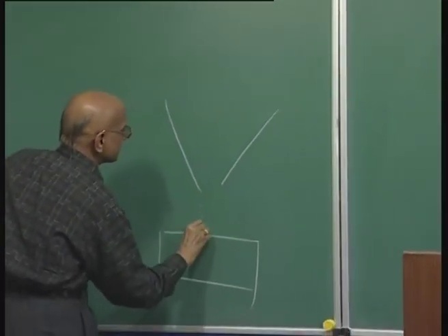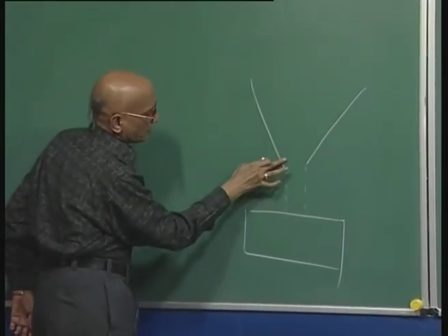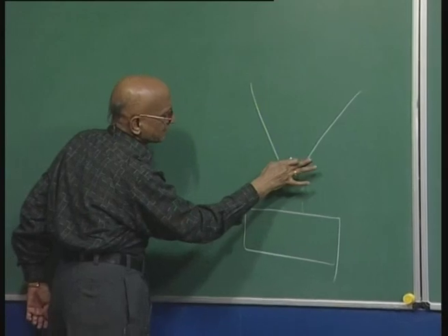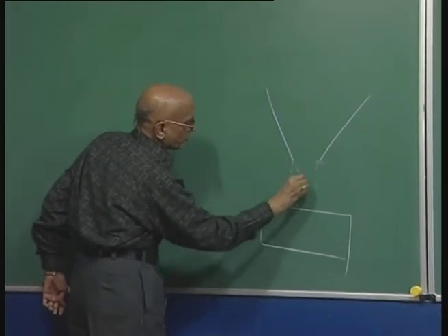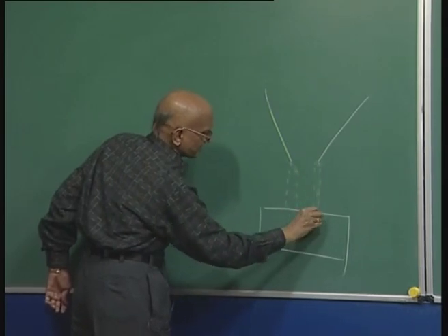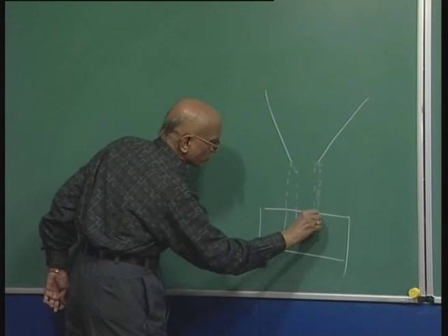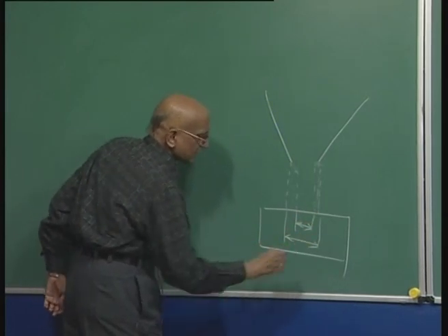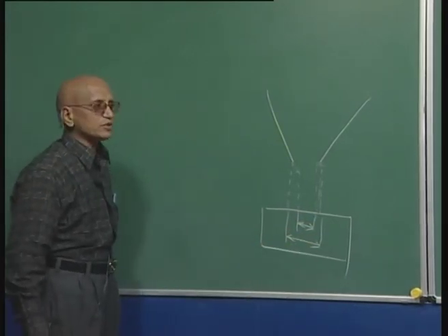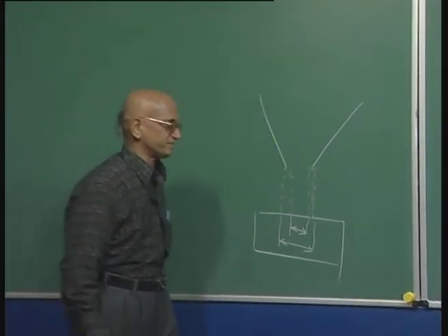Here, if you see the cavity, it is forming like this. Now, if there is an excess wear of the nozzle like this, then the cavity is going to form like this. Although you have designed machining parameters for this particular cavity, since the nozzle has worn out, you will get this cavity, which will not be good as far as your requirement of the components is concerned.